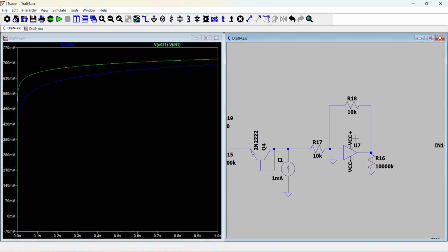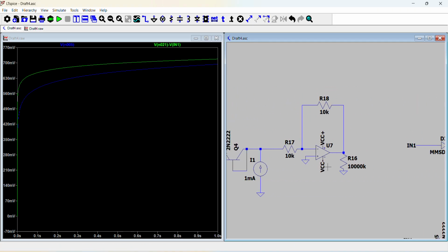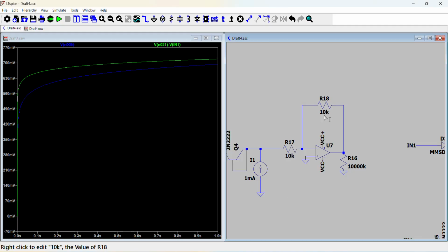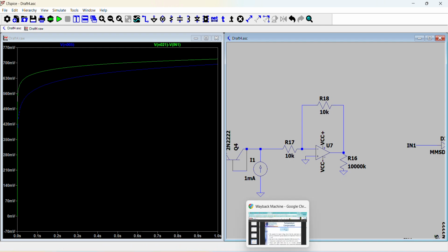And then likewise, there's usually a gain stage at the very end with a temperature-sensitive resistor to adjust the final multiplication that you want to adjust your output on. And that is because Vt is also affected by temperature. It's linearly affected, and Vt is proportional to Vo. So by multiplying the output, you can adjust for the difference in Vt that changes with temperature.